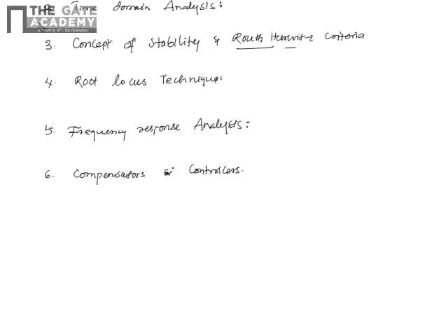One is the constant gain k, with values changing from 0 to infinity. That is one aspect to improve system performance, and the other aspect is compensators like RC circuits, passive circuits like a low pass filter or high pass filter. So lead compensators, lag compensators, and lead-lag compensators. That we'll see in this unit.